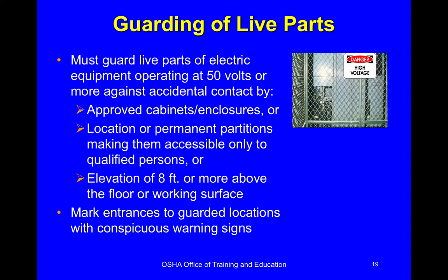Any live parts have to be guarded, usually by a fence. If they're above 8 feet above a working surface, typically they're not going to be guarded. Okay.